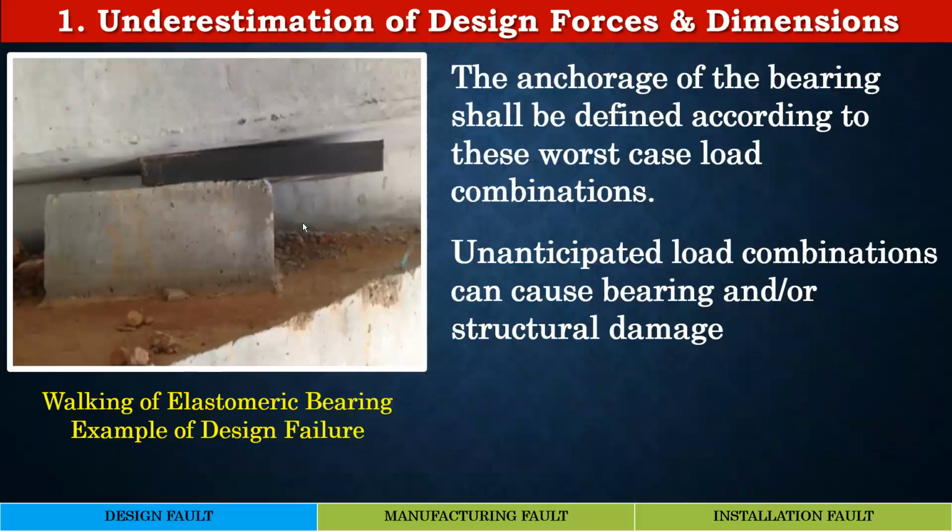This is another example of underestimation of the design force leading to failure. In this case, you can see the elastomeric pad, which is simply walking away, and this walking of elastomeric bearing happens when the minimum load is very low, and the friction between the elastomer and the concrete depends on the vertical load, and the lower the load, the less is the friction. So this is a scenario where if you overestimate the minimum load, then there is a problem of walking away of the elastomeric bearing, and this is one such example.